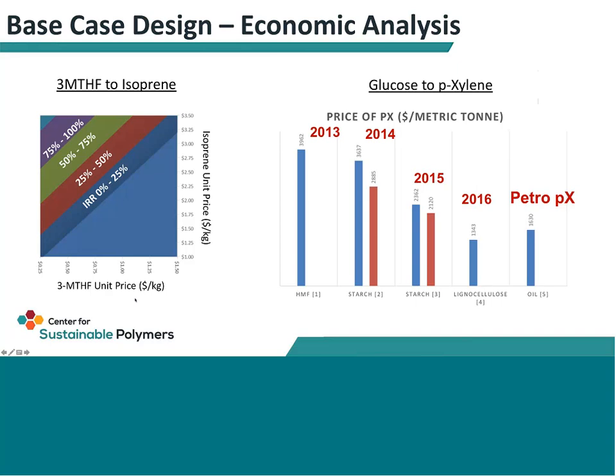And so what you can do, from your cash flow diagram, is generate a mix of all possible scenarios based on the prices of isoprene, the product, and the feedstock, and look at how the possible scenarios would play out in terms of what makes money and what loses money. You can even then do a Monte Carlo simulation of all the probability distributions of prices to look at how likely it is that you would lose money. And this can go into a whole field of forecasting and economics.